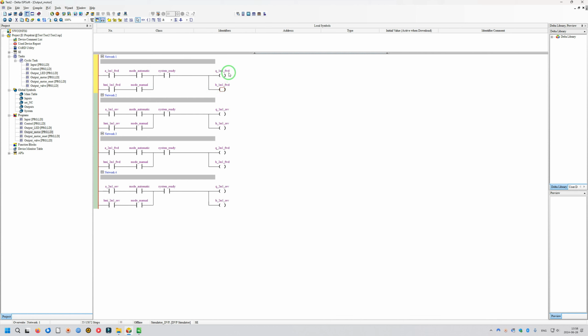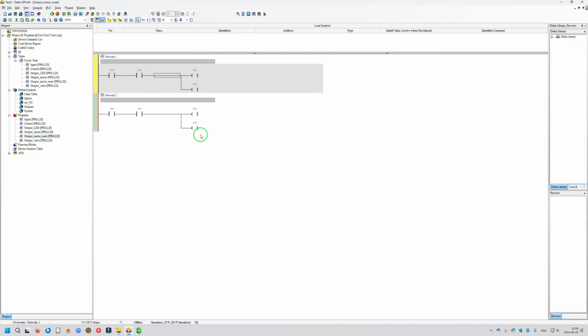And also in the program, so for example, my output failed, and I'm going to replace it with, for example, this one address. So I don't need to go to HMI to fix this address. Okay, so we have motor controls. Let's go to motor reset, and here we have Q1M1 reset, and here Q2M1 reset.